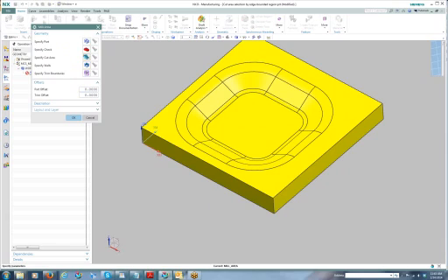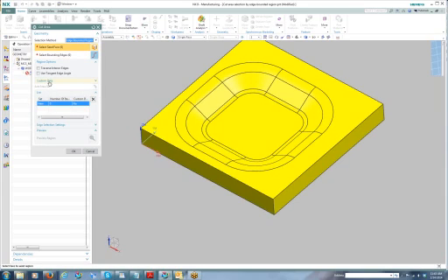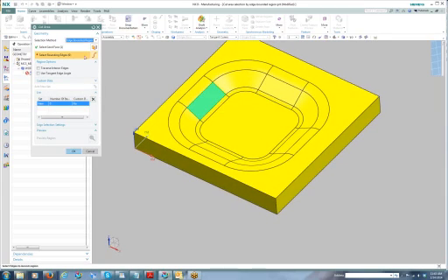So here I'll choose specify cut area, and my technique I'll use is called edge bounded region, where I'll select first a seed face, and then I say, well, here's the bounding edges, which could be this perimeter here, and then say this perimeter here going around the inside.